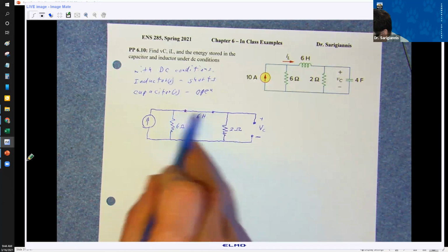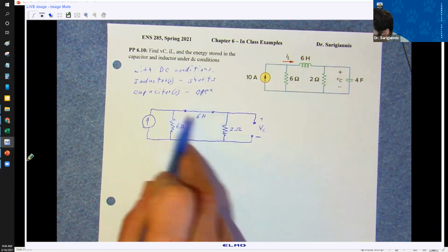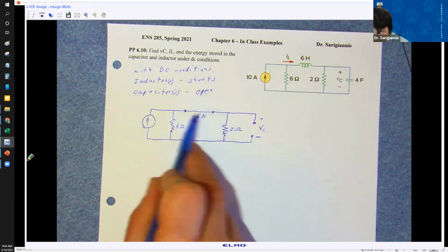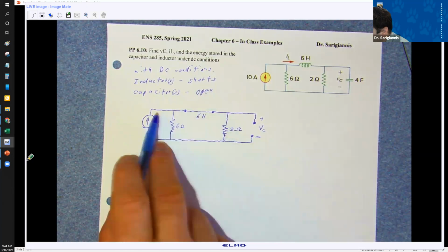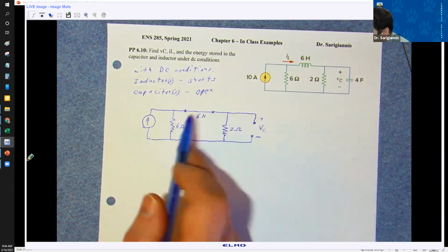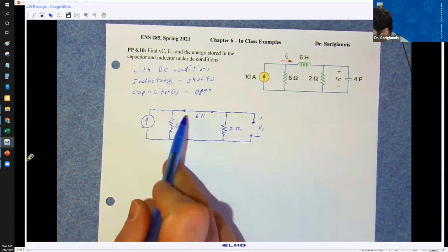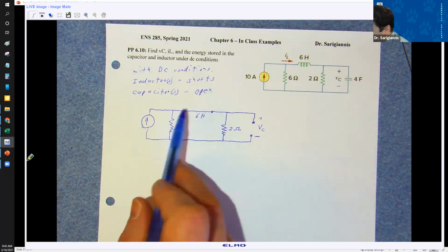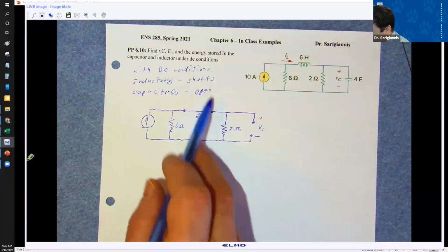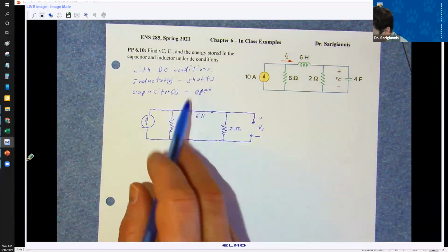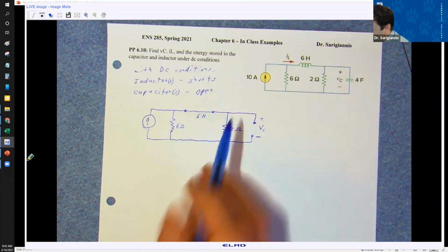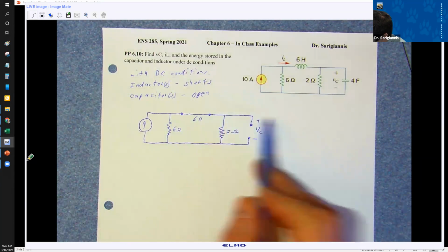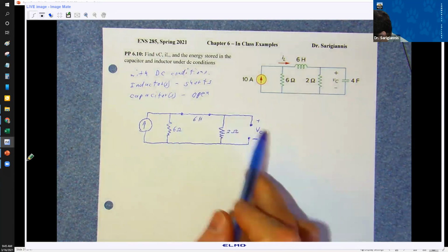Then after some time, you get this water wheel spinning at the same rate as the flow rate of water. So now the water wheel is basically stored energy. But what happens to the water? The water is just passing through as if there's no resistance, besides whatever the friction of the pipe is. That's why once you shut off the flow, the water wheel continues to spin and spins down, but it's pushing the water through. So that's your rise and fall in current with an inductor.